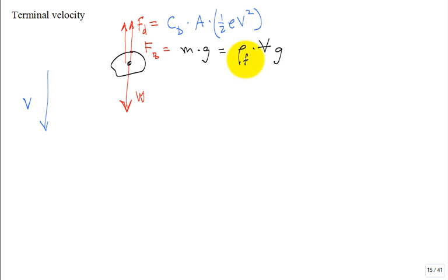So what is that rho of F? Or is that rho of the solid? No, it's the density of the fluid that's being displaced by the solid. So it's not rho S. A lot of people will put rho S. Let's say it's a copper sphere or something in water. They'll put the density of copper there. No, it's not that. It's the density of the water.